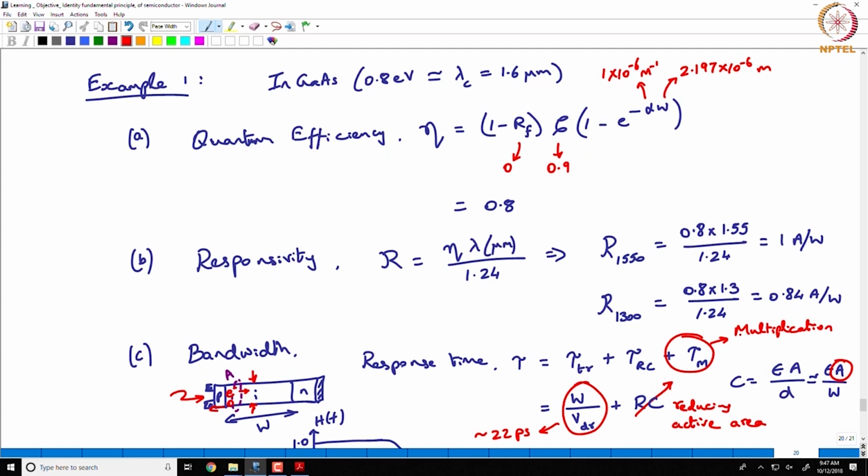So, it is actually serially multiplying, right, and so that will have a certain multiplication time. So, this factor you need to add for APDs. Based on this, you can tell that APD response is going to be always slower compared to the PIN response, right? You understand that? Because there is an additional multiplication time that happens in the APD.